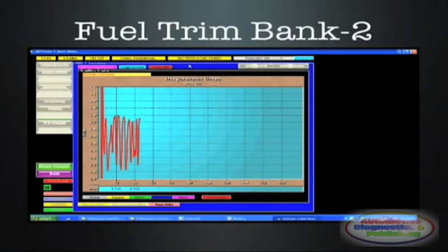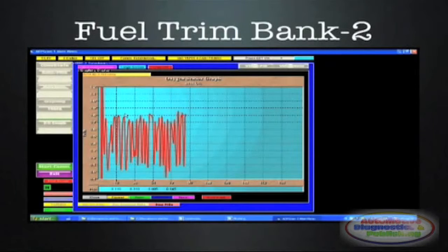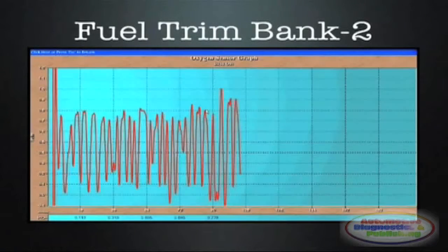Use the short term to check for vacuum leaks, together with any other technique, such as propane enrichment using the right tool. A minimum of 150 millivolts or 0.150 volts and a maximum of 800 millivolts or so, about 0.800 volts, is desirable.